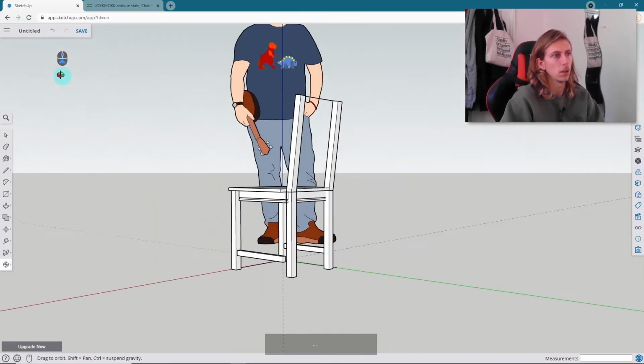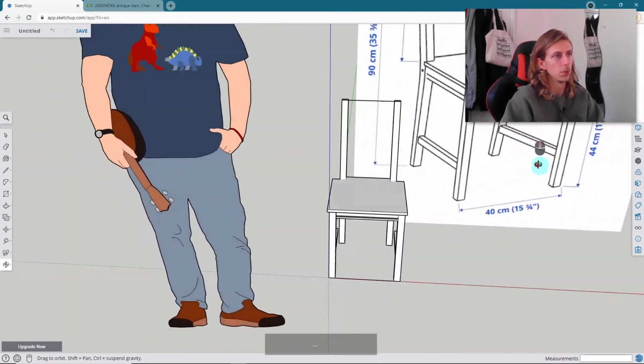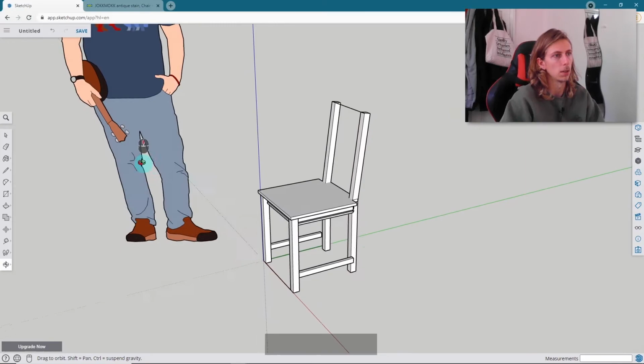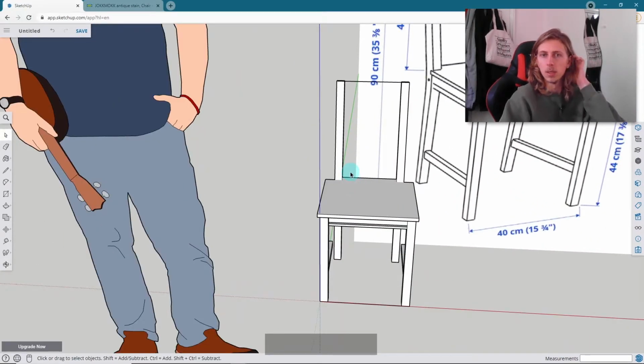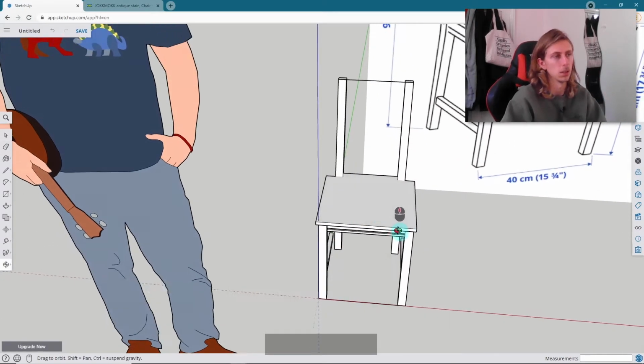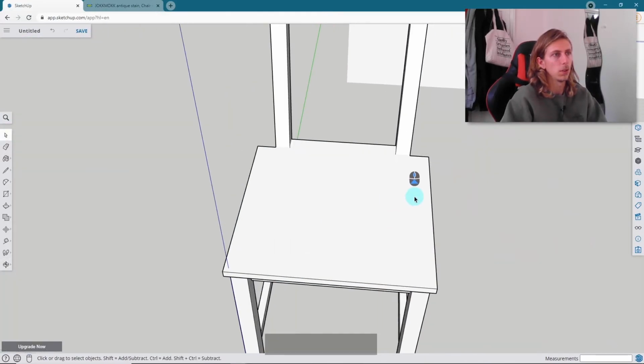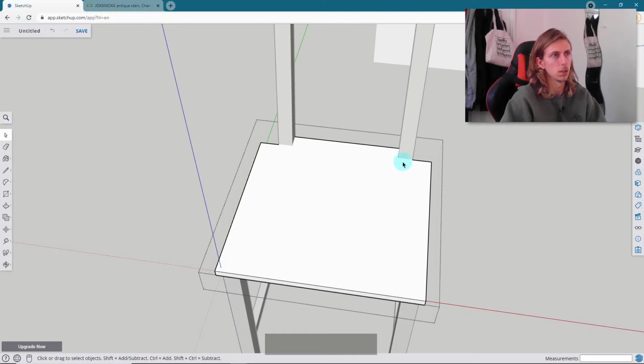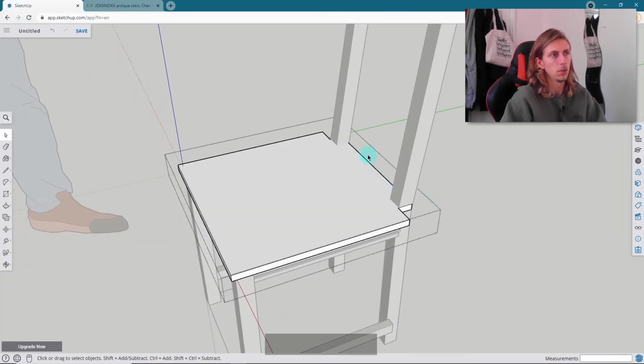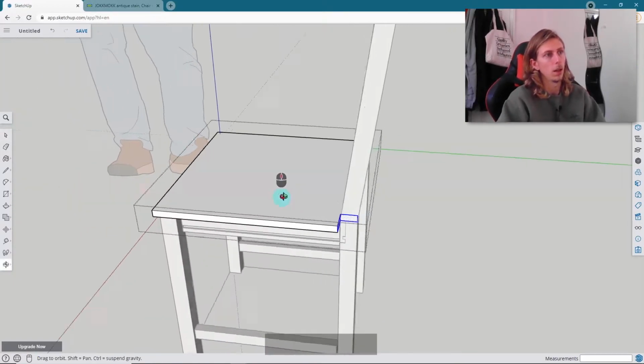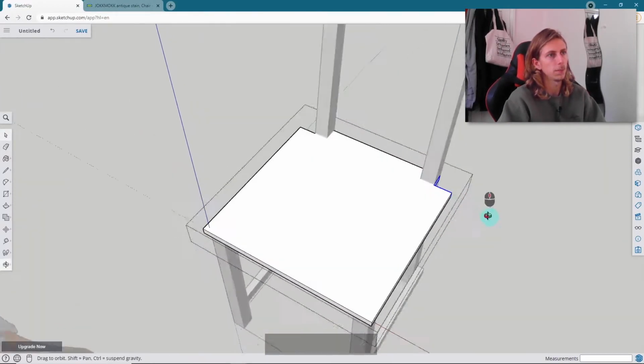Now you're probably thinking, oh, you've just ruined all your work, but we haven't ruined it. It just means we need to adjust the positioning of it. So the first thing I'm going to change is this. If I double click into this component and use the drag tool, dragging from left to right, I'll select these faces here only.